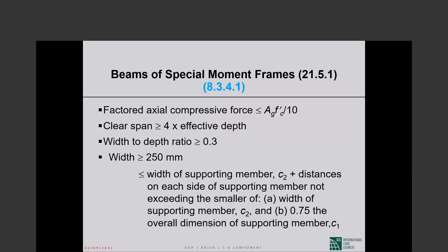So that 21.13.6 was already available, and it looked like a very attractive alternative to living with a limit that was very, very stringent. But I emphasize, I never said that flat plate column frames cannot be used in design category D. No, they cannot be used as part of the seismic force resisting system. There is a huge difference between the two statements.